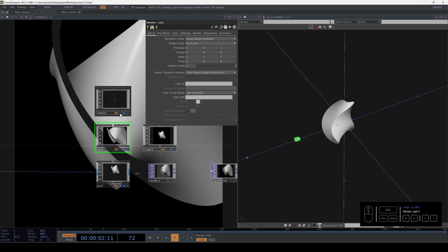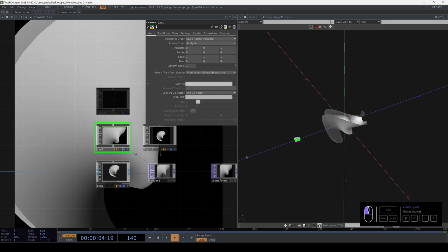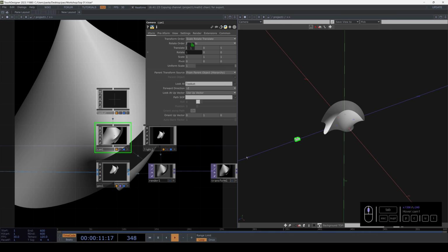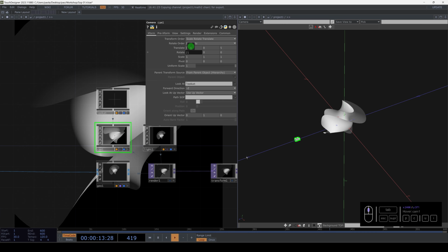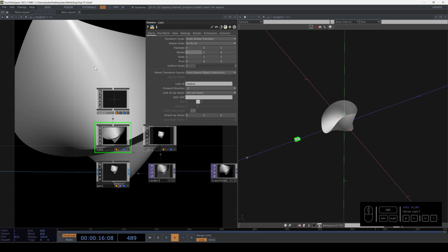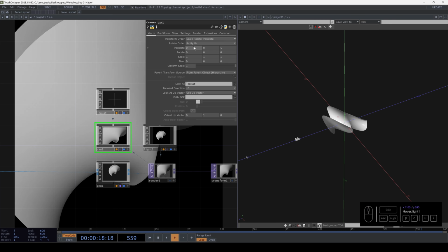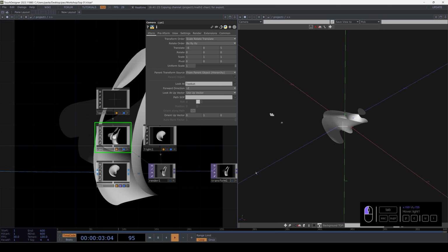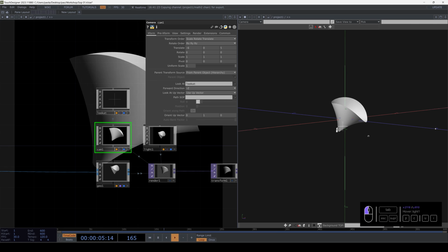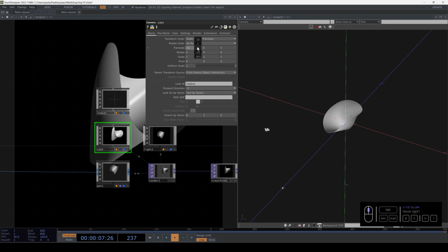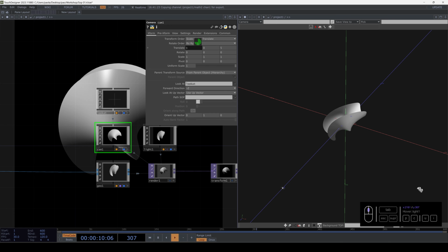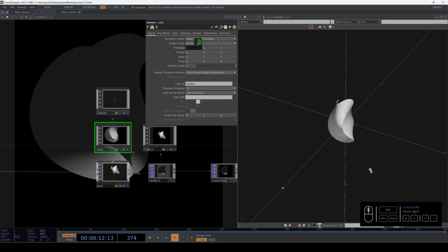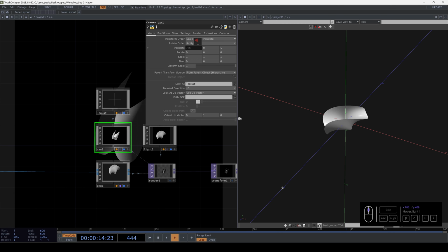So in the camera, I'm going to the look at parameter and release here, look at. So right now, when I rotate the camera, nothing happens because its rotation is just looking at the point. Right now we need to change the position. And then when I do that, no matter what I do, the camera rotates on its own, all the time seeing the object. It's there all the time, no matter what you do.